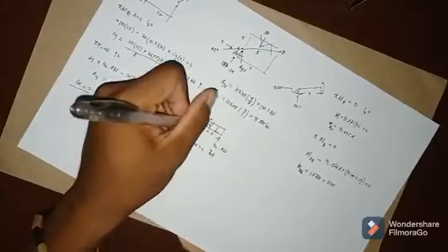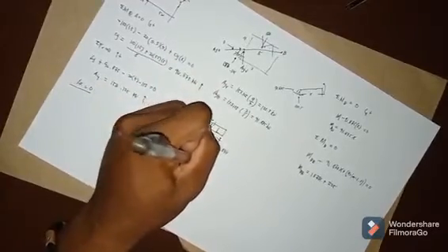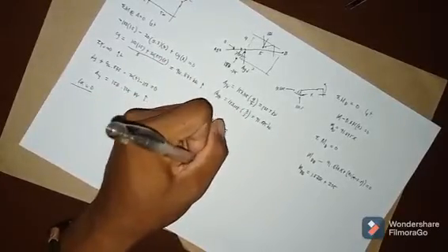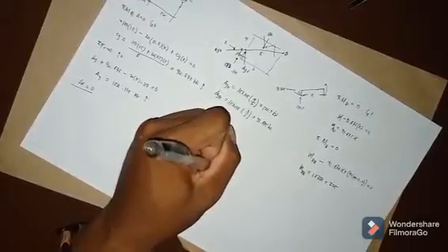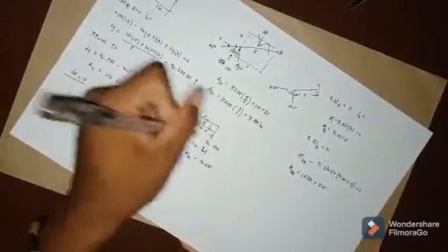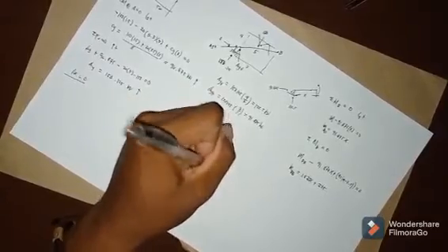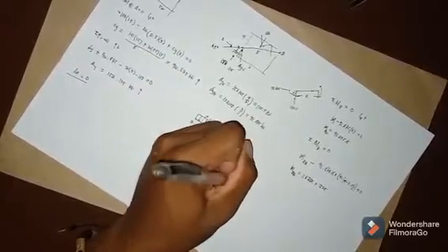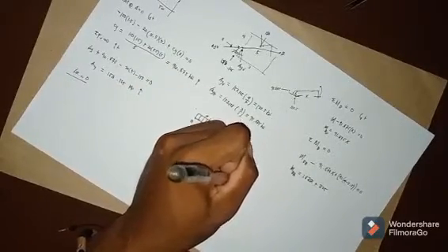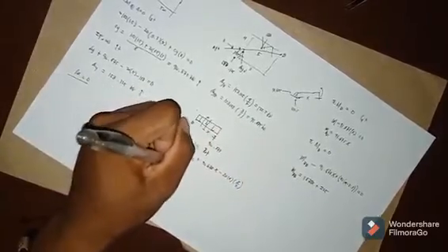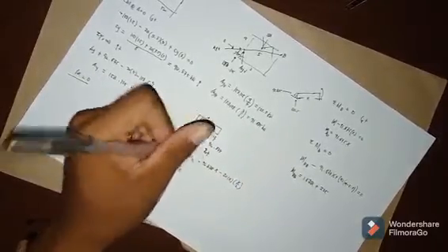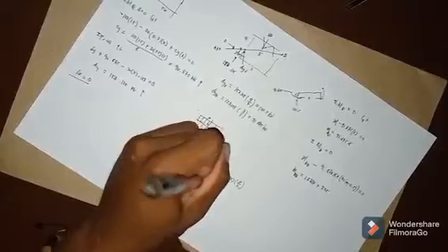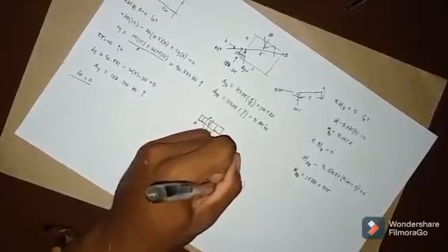So it is rotating clockwise, so negative moment of BC plus yung concentrated load 96.875 x times the arm length, which is x, minus 20 the distributive load times x times the centroid, which is x/2. So moment at BC is equals to distribute, so we can get 96.875 plus 10x raised to 2.